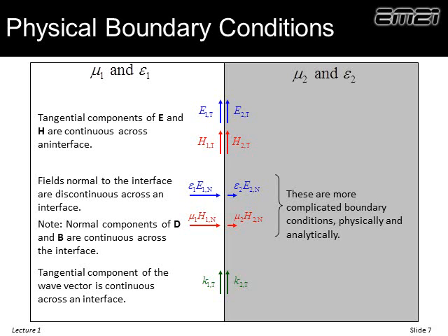Like last semester, we discussed two types of boundary conditions, and to differentiate them, we called one the physical boundary conditions, and the other we call numerical boundary conditions. The numerical boundary conditions were where we were writing some kind of equation on a grid, and at the edge of the grid we needed values from the outside, and we needed to know what to do about that. How we handled that we called a numerical boundary condition.